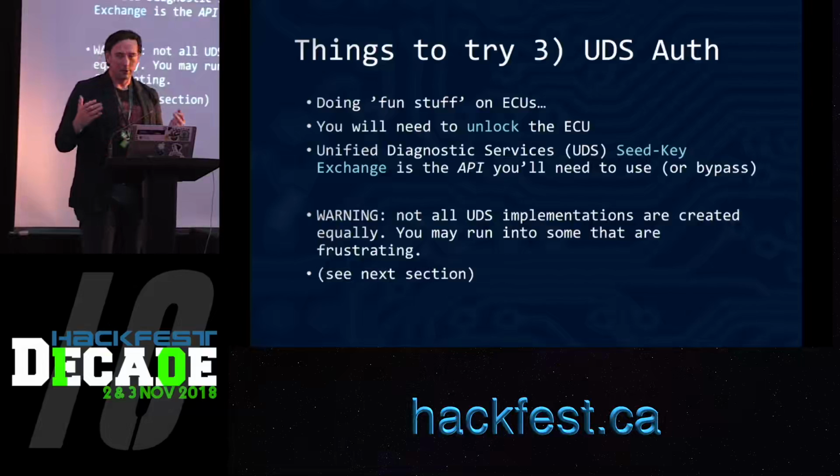What is OpenXC? Ford makes these dongles. They're kind of like the SocketCAN adapters we talked about, except that instead of showing up in Linux as a USB device, these things show up as a Bluetooth device. And then they defined a protocol over Bluetooth using JSON so that you could develop an app, say for your phone, that knows very generic names for certain signals like tire pressure or velocity. And then the app could be the same, but you could have different cars, right? So I've got the same app, but totally different models of Ford, and the app would still work with all the Fords.